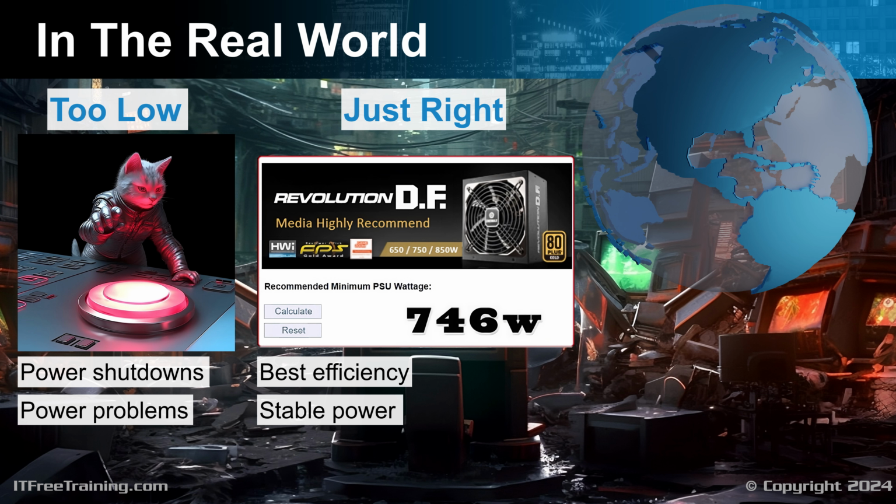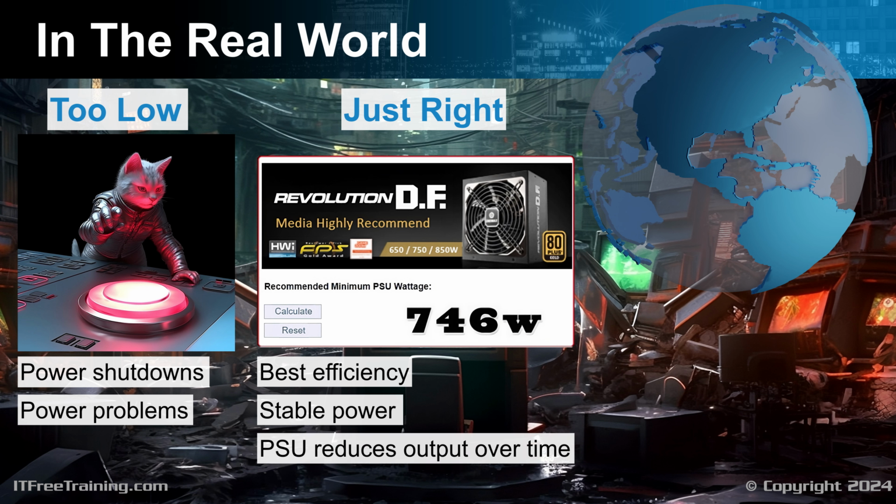It also gives you stable power. The power supply calculators are good tools, but the math they use to give you the result is hidden, so you never really know how close it gets to the real value. Generally, I would use one of these and round the result up a bit. In this example, I would get an 800 watts or 850 watts power supply, but would not go over that. It's important to understand that as time goes by, your power supply unit reduces output. Essentially, the capacitors in the power supply start to wear out. So, I like to leave a little extra capacity to allow for wear and also for future expansion.